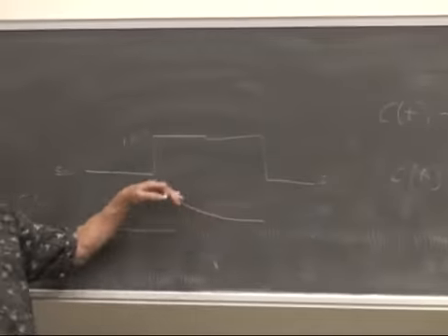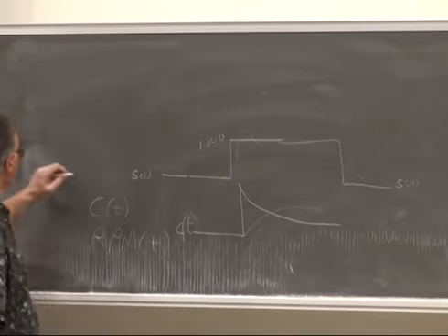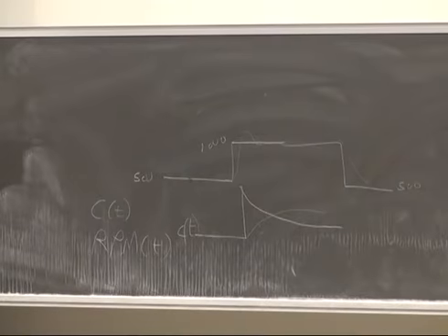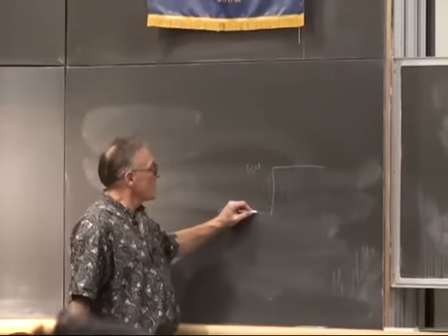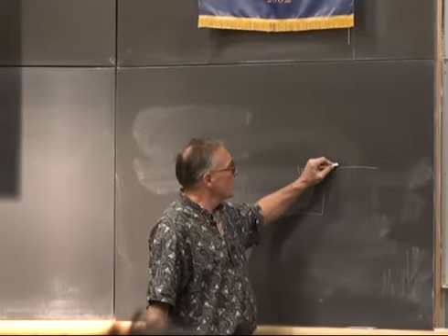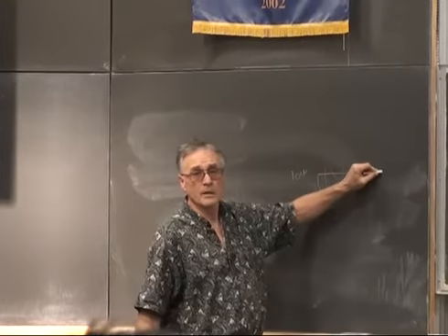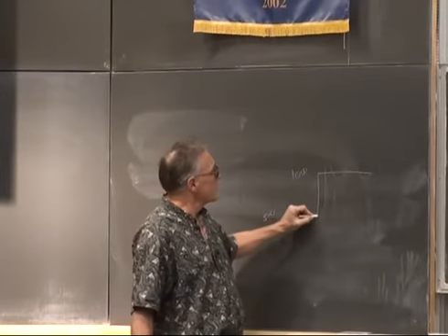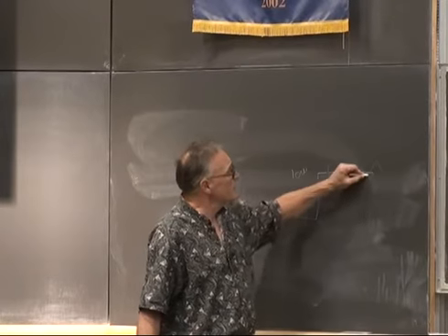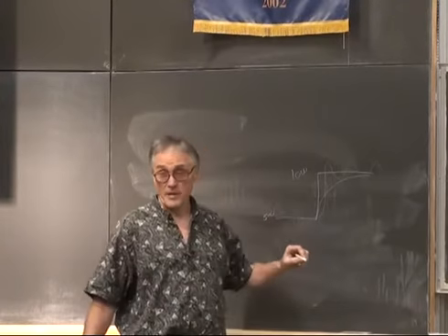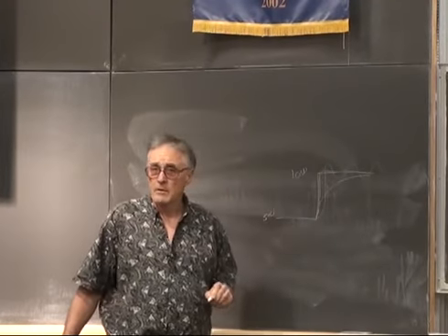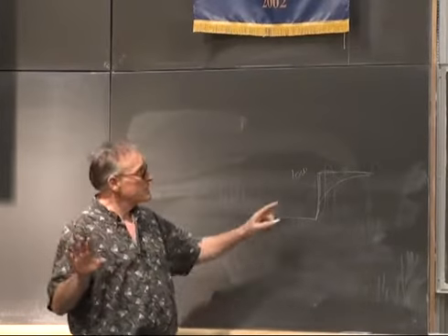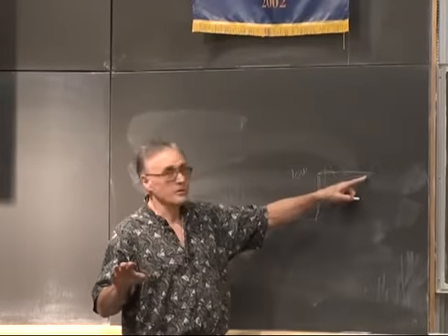What I'm interested in is the shape of these. For instance, when you step from 500 to 1,000 RPM, does the system oscillate forever? Does it approach exponentially? Does it do the optimum thing and overshoot just a little bit and then settle? So we're going to be interested in settling time and accuracy.